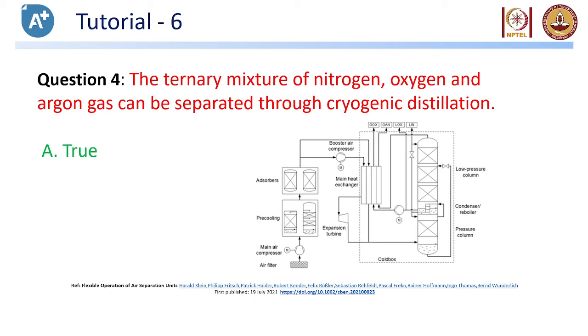This is one of the setups of an air separation plant, which we will simulate. We will start this flowsheet simulation today, but it will take a good amount of time to finish. Purified air is compressed in a multi-stage compression system and pre-cooled. Absorption is used to remove impurities, and two types of sieving materials are used: molecular sieves and activated alumina.